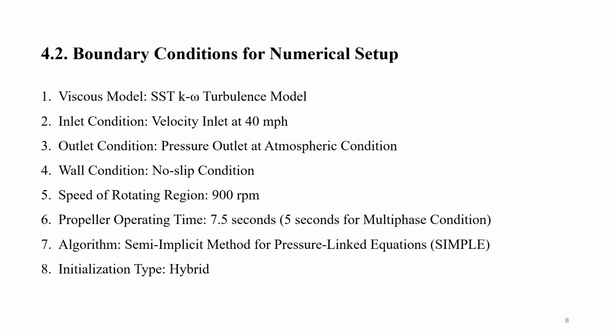For the fluid outlet condition, a pressure outlet has been employed. The stability and convergence of the simulation are facilitated by the use of the semi-implicit method for pressure-linked equations algorithm. This algorithm is chosen for its stability characteristics and its ability to converge towards a solution predictably.